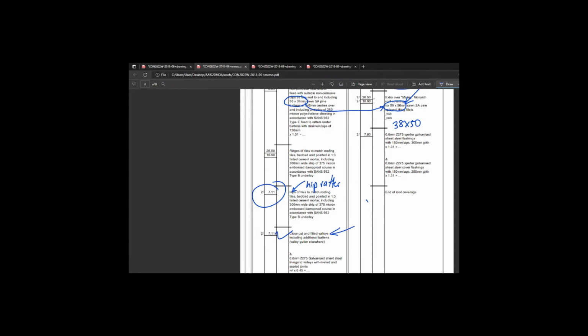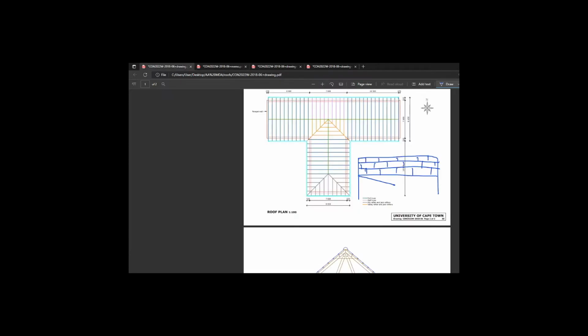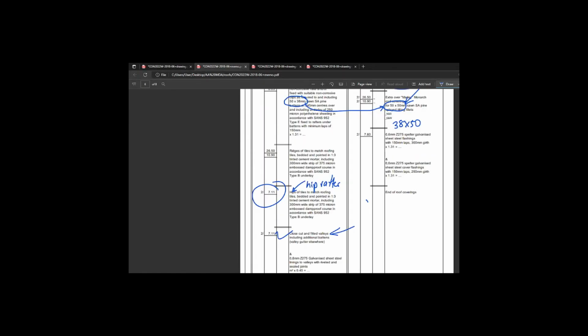And at the interface where the roof meets it, let's just say this is a mono-pitch roof to make my drawing easier, it's sometimes stepped, and you will see it in public as a step flashing. Stepped like that, it needs to be parallel with the earth, so as it steps, it runs down, right? And you need a cover flashing. So there's two things going on here: flashing and a cover flashing.